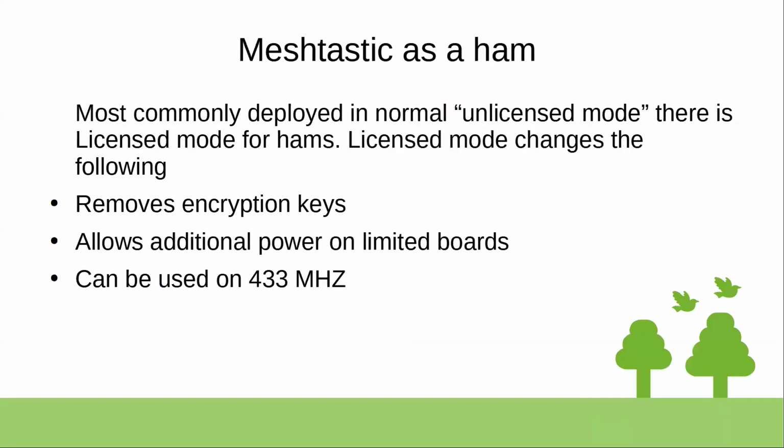And just as a note, if you change away from long fast, you also no longer benefit from the larger mesh. Because it's like the modem basically. So if you change the modem, it's a different kind of preset. So you can't hear each other once you change it. Right. Yeah, so if you're not hearing anybody whatsoever, double check those settings. Long fast, frequency slot 20 in United States.